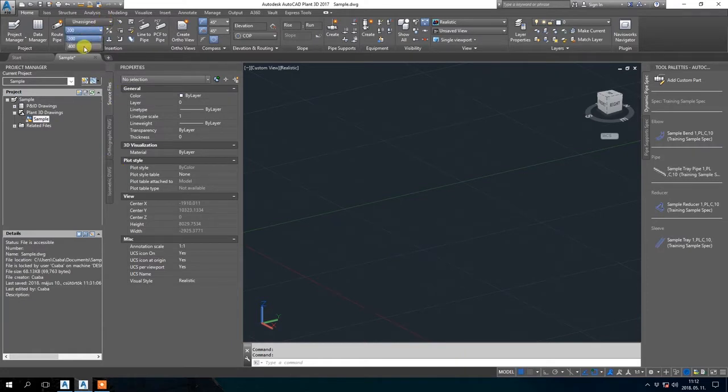And we have the available sizes of 200 and 400. And as I told you, this availability is checked by Plant by the available pipe sizes inside your spec. So that's why we have added this pipe into the spec and into the catalog, because we need the pipe to trick Plant to assume that these sizes are there. And it is really there, but we won't use this pipe.